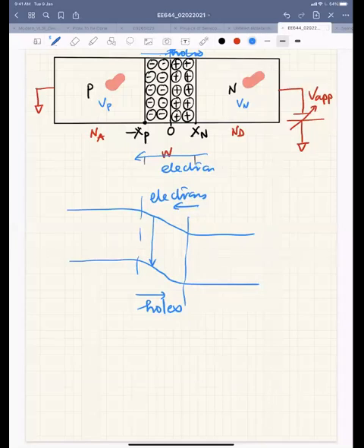But when you talk about a PN junction, if you see how it is fabricated, you had a P layer, then you implant an N layer. During this implantation, the junction has some damage. When you do implantation, you create a lot of damage. Then you anneal the silicon, and when you anneal, these damages are healed. So you just get rid of those damages.